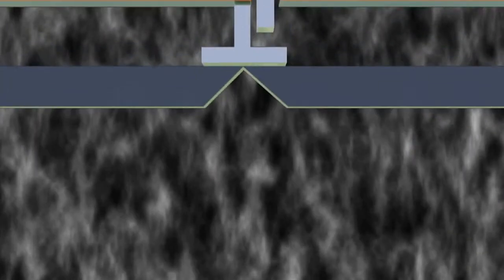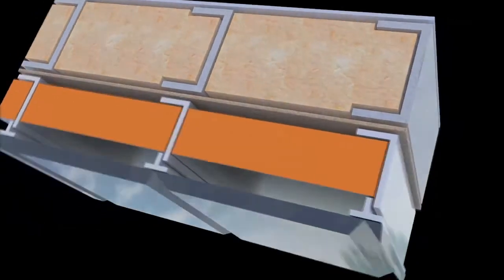Transfer by convection occurs when airflow acts as a transport mechanism, carrying moisture in or out of buildings. Holes, cracks, penetrations and leaky ductwork may all provide potential pathways for moisture movement. As the moisture passes through the building, it will condense on surfaces with temperatures that are below dew point. Condensation levels will be affected by the difference of temperature between inside and outside, relative humidity and the speed of air movement. Moisture can also be transported by capillary action.